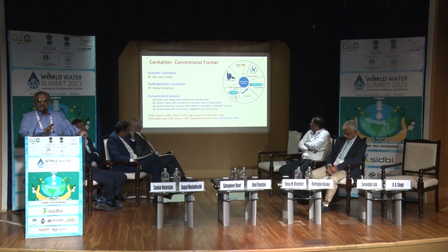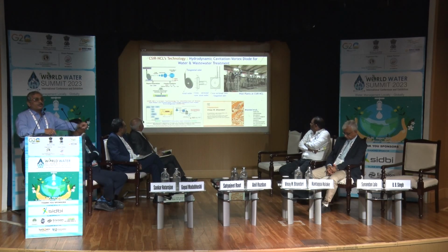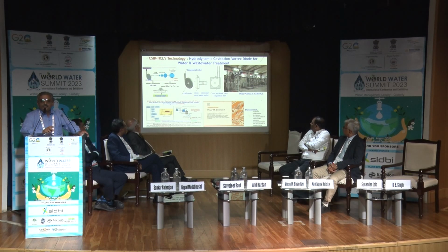But the devices that are used for hydrodynamic cavitation are commonly orifice, venturi, and things like that. And they are more academic in nature. They were not successful in industry because of their poor efficiency and of course cost of operation. And for industrial dirty wastewaters, they are not suitable. So for practical applications, they were not suitable. That's why we developed a new device. Next one. And this slide shows the design of our device. We call it the vortex diode. It has nothing to do with an electronic diode. It is just the name.